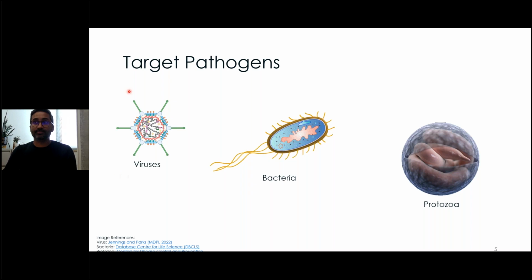And chlorine, for example, with viruses and bacteria is actually really effective. It can get in through the wall, it can damage what's going on inside there quite well. When it comes to protozoa, it's actually a little bit harder because this outer shell is quite thick and hard to get through for chlorine.